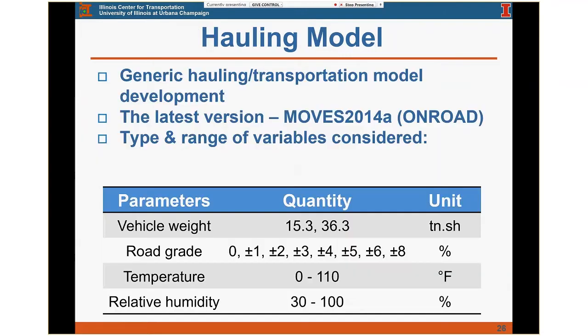And one thing that we really paid attention to in the tool is the hauling and construction equipment. Because we know that when you compare in-place recycling techniques, the benefits can only be realized if you can accurately capture the hauling-related impacts associated with the conventional production and transportation of the asphalt mixture to the job sites, because that's the one that's being avoided in the in-place recycling operation.